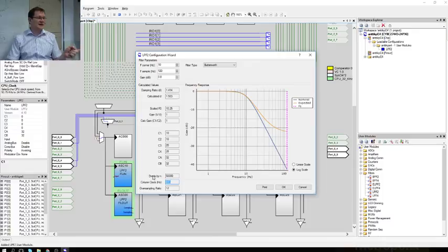You cannot generate it using this VC1 to VC3 anymore, since this is only 400 hertz, and you need a divider of 50,000 from the system clock.